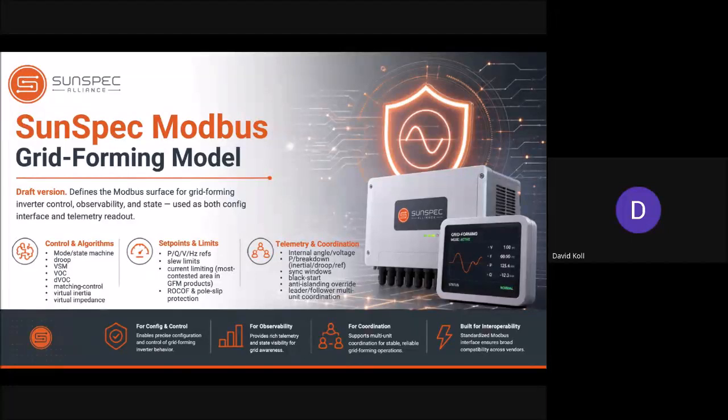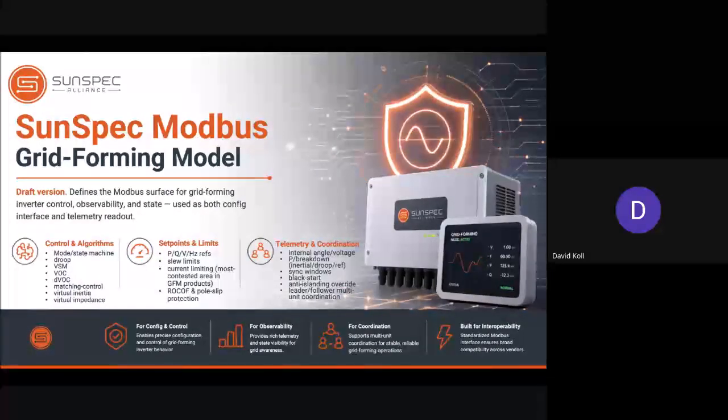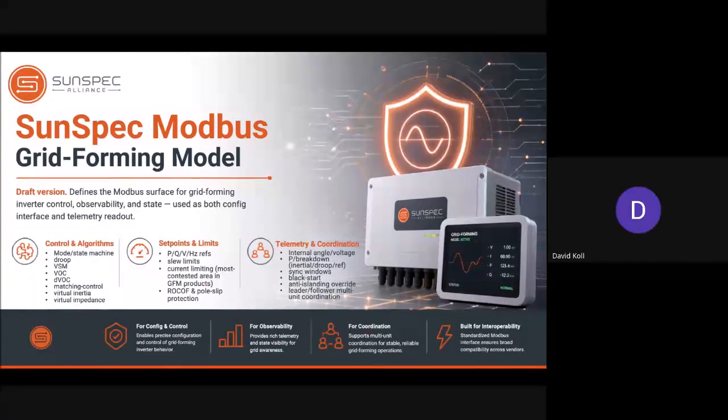This is where the grid forming device potentially can offer a solution to bridge the gap between grid following and the real world interactions. Grid forming devices are controlled voltage sources capable of creating the grid from scratch, typically using software-driven synthetic inertia to allow balanced networks that can self-regulate. Grid forming devices do not look to track or sync with a leader. It in fact becomes the leader by generating its own stable internal voltage phasors.